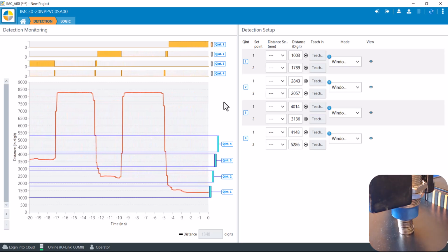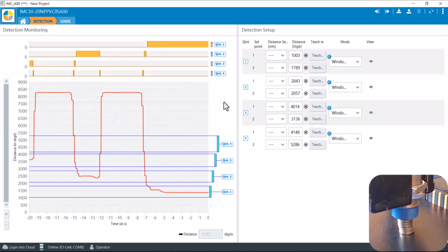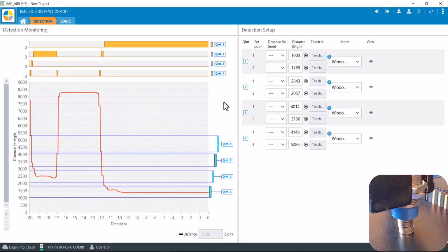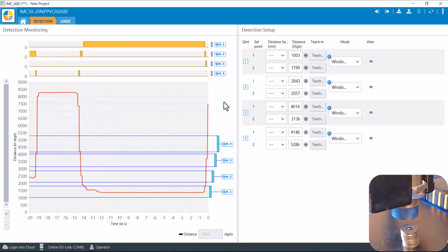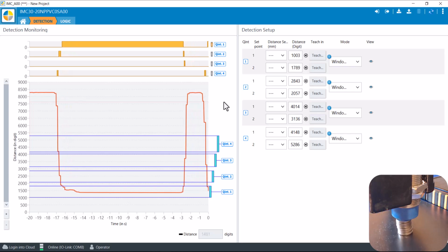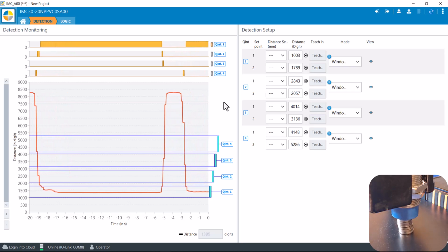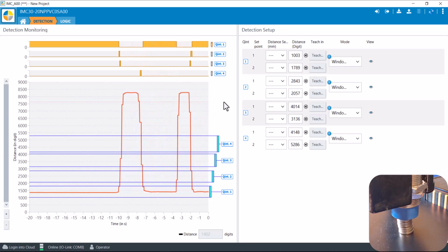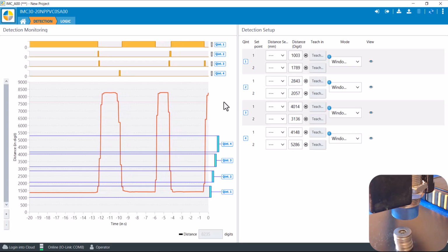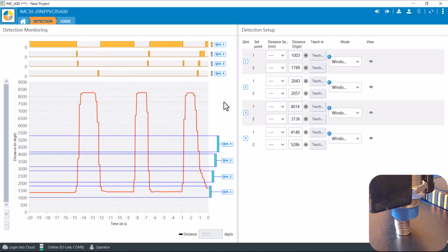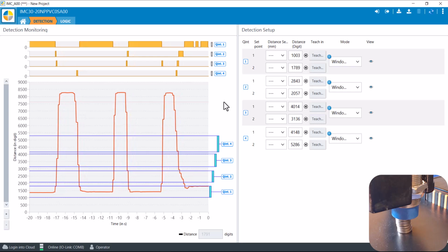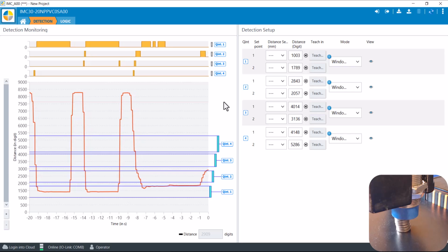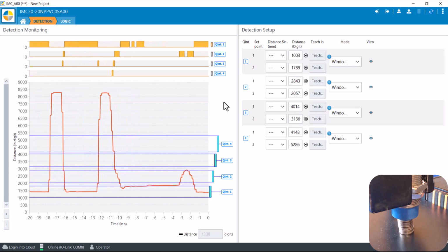So with the IO-Link chip in it, the IMC sensor really does distinguish pretty well how many of these parts are underneath it at any given time. It looks like a pretty easy difference to tell. So I can set up these outputs, or again over IO-Link I can send that distance data and create my own windows. I have to make sure I put it in the right spot every time for it to hit that window.